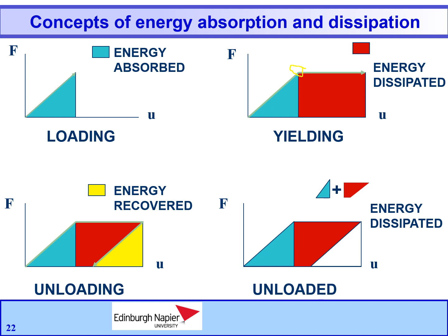In the general case, the force deformation relation for a structural member undergoing cyclic deformations expected during earthquakes is path dependent, which means that it depends on whether the deformation is increasing or decreasing.